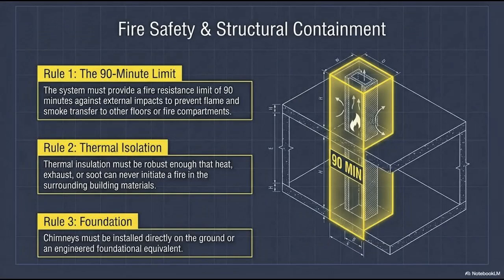The technical standards dictate that these coaxial systems must maintain a rigorous 90-minute fire resistance rating for high-rises. Meaning they can be completely engulfed in a direct, raging fire for an hour and a half without their structural integrity failing or the fire breaching the inner compartments to spread upward. Correct, or 30 minutes in lower residential buildings. It isolates the hazard completely. By adopting the LAS, the entire building effectively transitions to that foolproof Type C methodology. The mechanical lungs of the building are hermetically sealed off from the living spaces where humans breathe.